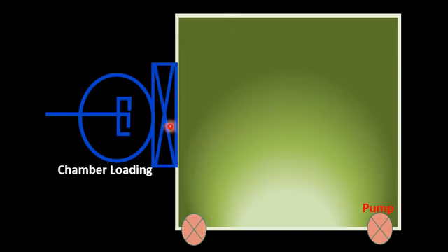Please note that if the vacuum decreases, or if our samples, which are our precursor materials, are freely exposed to the external environment and introduced inside the reaction chamber, there is a possibility of a decrease in the high vacuum, and it becomes quite difficult for molecular beam epitaxy to create the vacuum pressure of 10 raised to the power -8 to 10 raised to the minus 10 torr again.